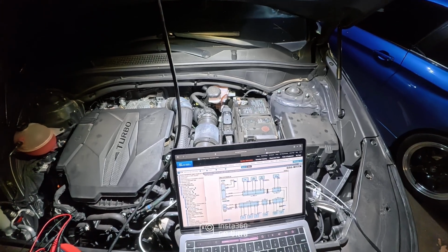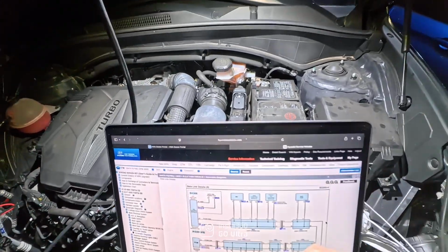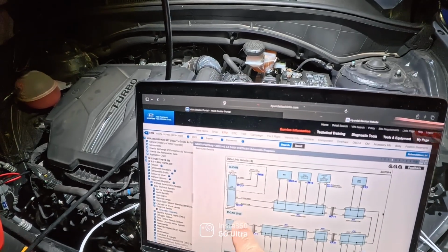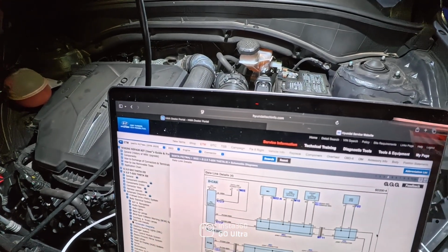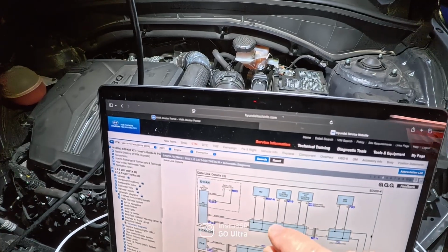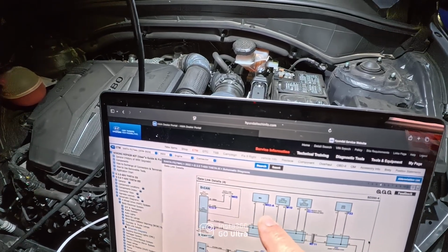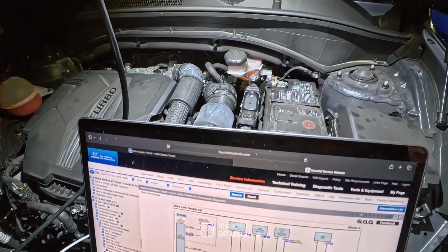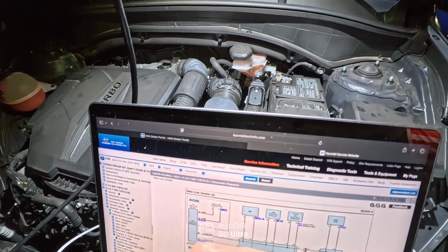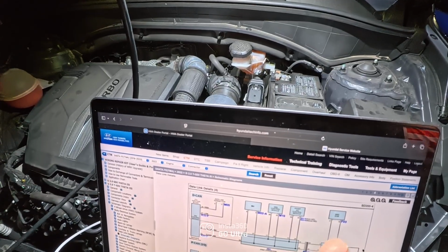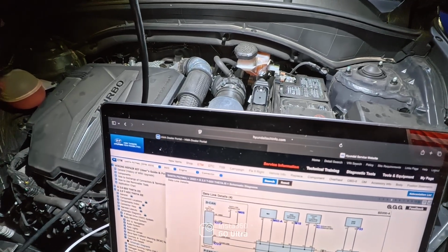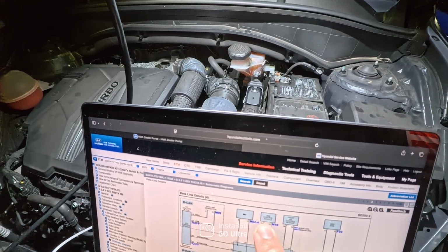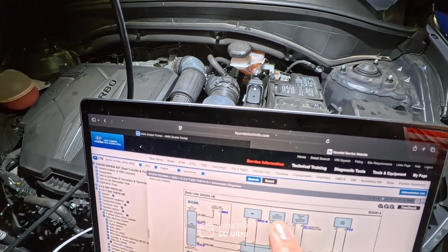I have seen in the past as well joint connector issues like a backed out pin, but usually that doesn't bring down the complete CAN network. Usually that's a shorted line. But if you had an SRS module that says failed communication, obviously you're going to check your module power and ground.